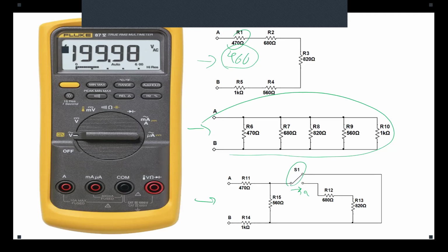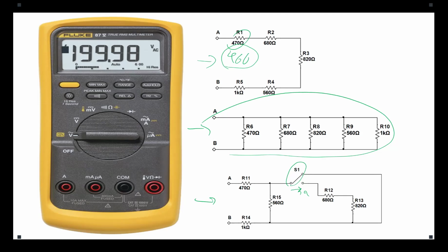I believe you have two or three of each of the resistors in the package that you are going to get the first time you are in the lab. If you use the same resistor, it's not going to change. There is going to be some measurement error, by the way, which brings the uncertainty principle into play. For all your measurements through the semester, you have to calculate the uncertainty of your measurement. We are going to be professional engineers. It's not just haphazard measurement, just reporting some numbers. You have to always calculate the uncertainty of each measurement, meaning you have a statistical analysis over your own measurements.